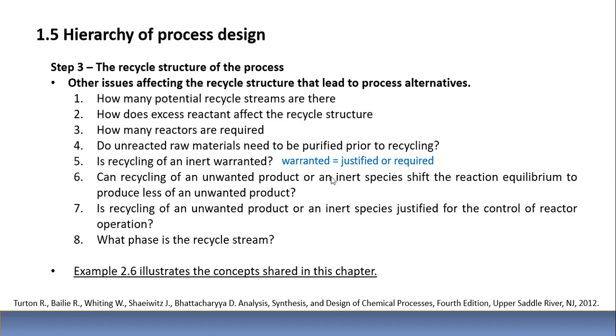Other issues affecting the recycle structure that lead to process alternatives will be how many potential recycle streams there are, how excess reactant affects the recycle structure, how many reactors are required, and whether unwanted raw materials need to be purified prior to recycling. Is recycling of an inert warranted?